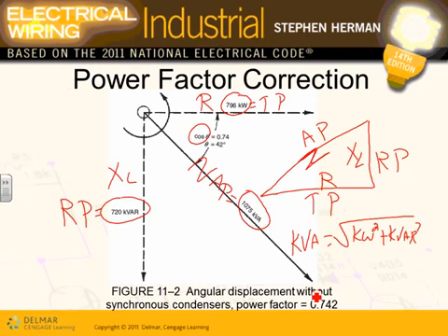So when you find the apparent power, my power factor would be the true power, which is 796 kW here, divided by the apparent power, which is 1075 kVA. Divide these two numbers and you will get 0.742. Any questions, Adam? Any comments? Correcting power factor, that's how we did it in the second semester. What we're going to do for correction is slightly different, using the same concept but using tables, in a few seconds when they do the calculation.